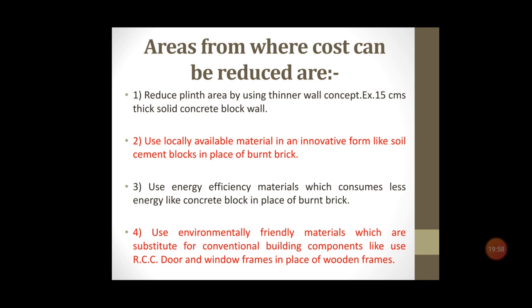Reduce plinth area by using thinner walls. Use locally available material in an innovative form. Use energy efficient materials which consume less energy. Use environmentally friendly materials which are suitable for conventional building components. Various examples are available.